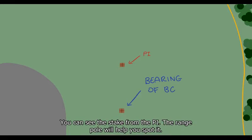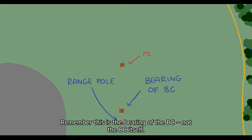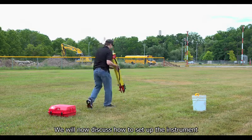You can see the stake from the PI. The range pole will help you to spot it. It is also marked with an X, similarly to the PI stake. Remember, this is the bearing of the BC, not the BC itself. We will now discuss how to set up the instrument.